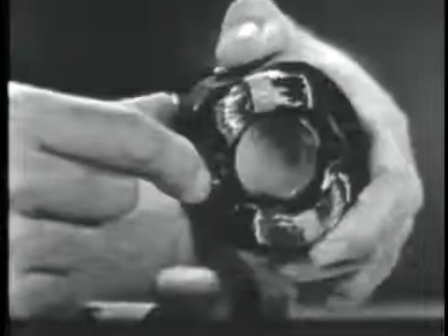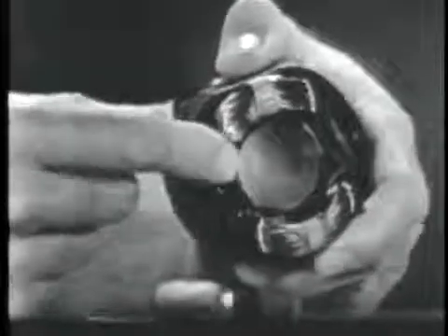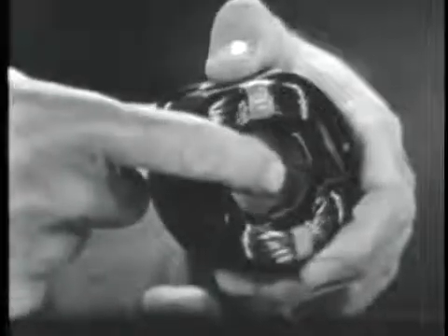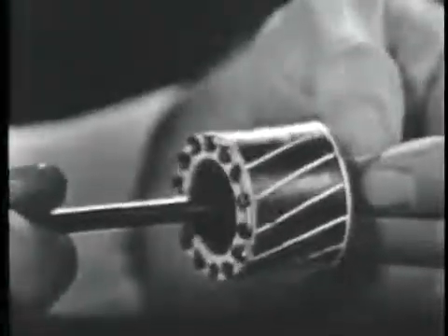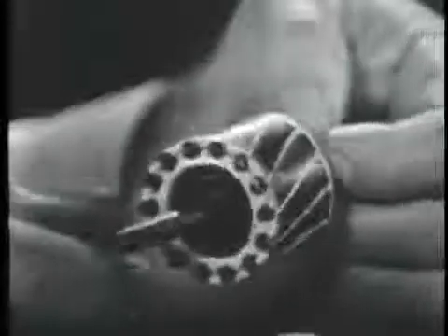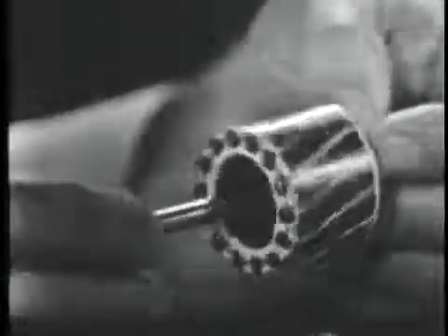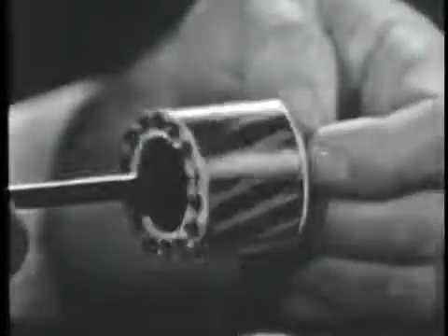Now, notice the simplicity of construction. We have the stator field windings, the iron core. Very, very rugged and very simple. Inside the stator field windings, the rotor. Let's take a look at this rotor. All right, the rotor has no commutator, no slip rings, and no wire windings. It doesn't look at all like the rotor used in DC motors, does it?